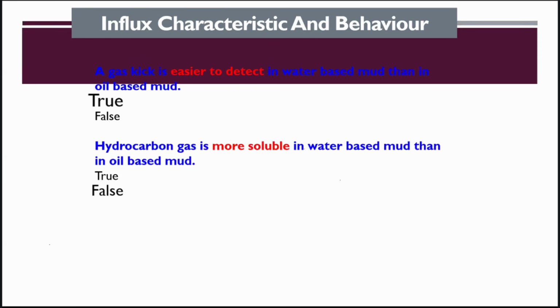A gas kick is easier to detect in water-based mud? True. If we are using water-based mud, it is easy to detect a gas kick. And if we are using oil-based mud, hydrocarbon is more soluble in oil, not in water. So this statement is false. Hydrocarbons are soluble in oil, so it is hard to detect.